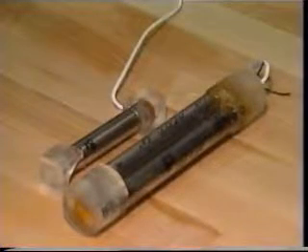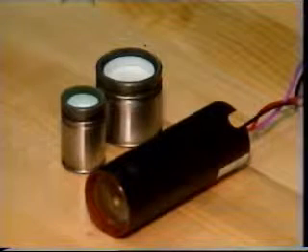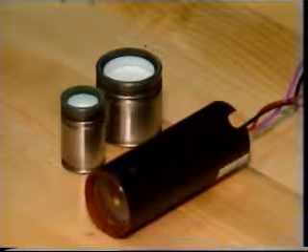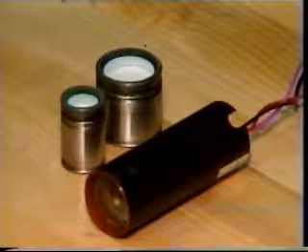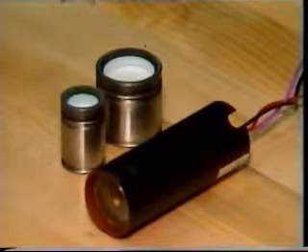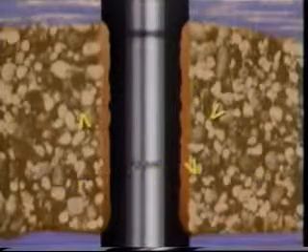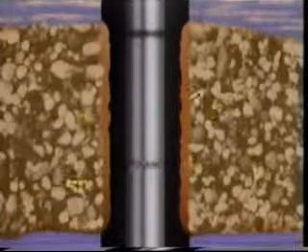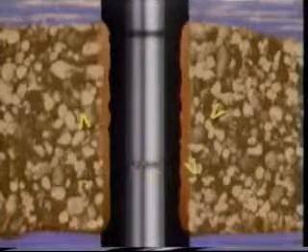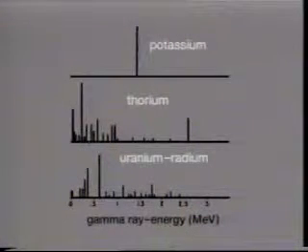The conventional gamma ray tool consists of a Geiger-Müller counter or a more sensitive sodium iodide scintillation detector in crystal, which counts natural gamma ray emissions for fixed intervals of time. These emissions originate through the natural decay of radioactive elements in the formation surrounding the borehole. The radioactive elements are due primarily to uranium, thorium, and potassium.